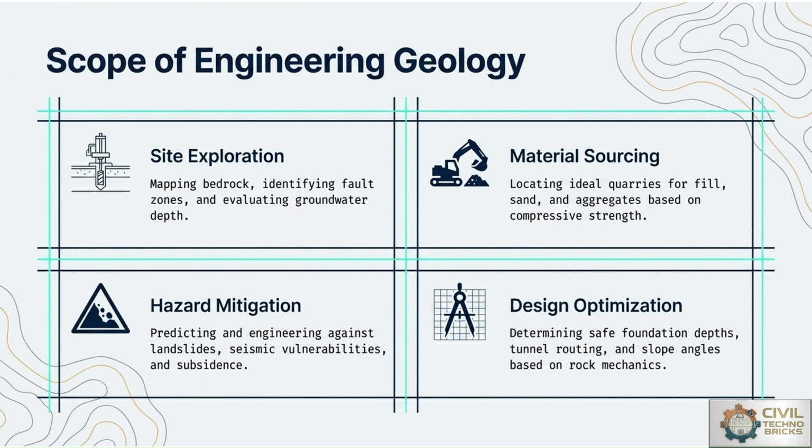Third one is hazard mitigation, where the prediction and engineering applications, or we can say the prevention and mitigation techniques for landslides, seismic vulnerabilities, and subsidence, are important. Fourth one, design optimization, uses geological data to improve structural safety and economy. So determining safe foundation depths, tunnel routing, and slope angles based on rock mechanics is most important. From the civil engineering point of view, engineering geology supports all stages of planning, design, construction, and execution.